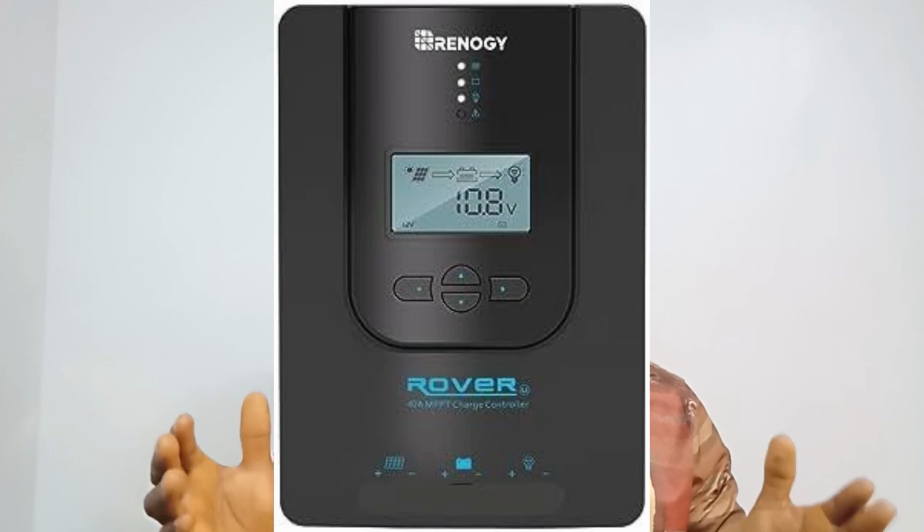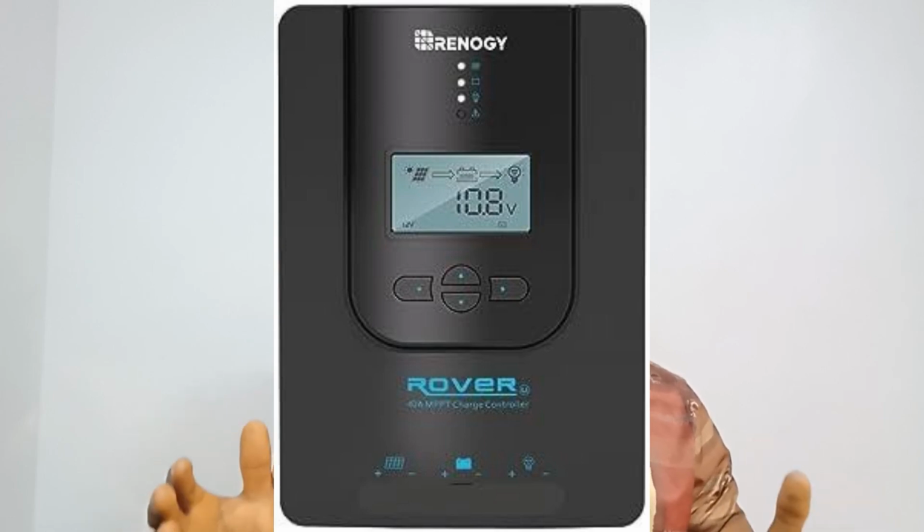Then we move into the second type of charge controller, which is the MPPT charge controller. MPPT stands for maximum power point tracking. The MPPT charge controller tracks the maximum power point of the voltage and current for the solar panels going into the battery. For an MPPT charge controller, excess voltage is converted to current to charge the battery faster. And MPPT charge controllers have a higher efficiency, between 95% to 98% efficiency.